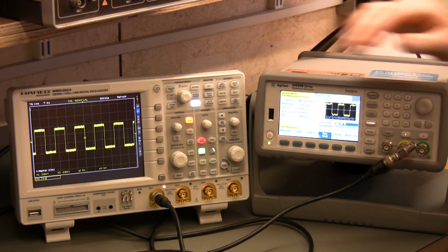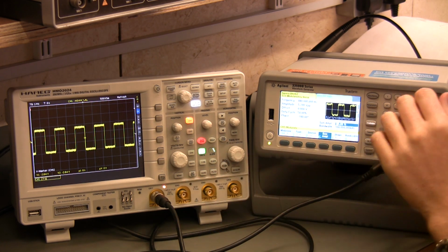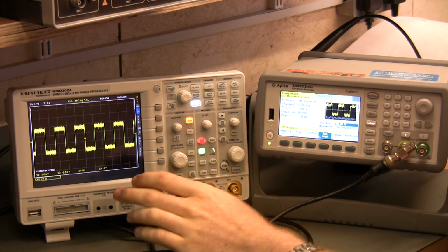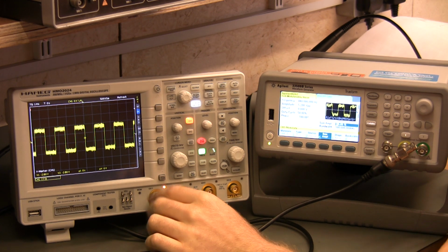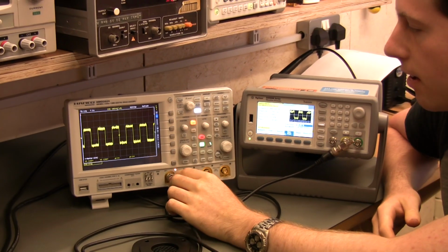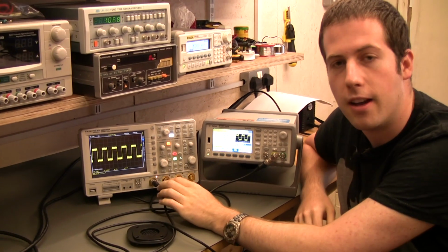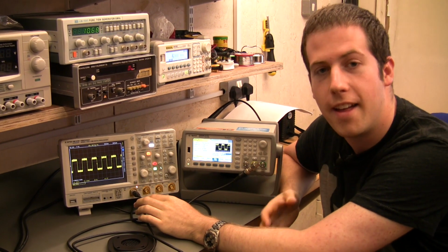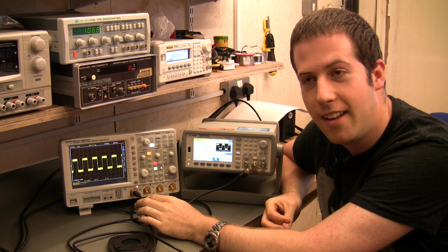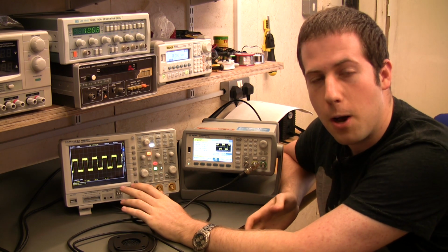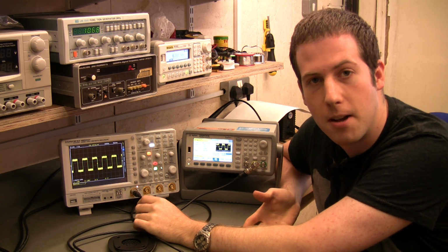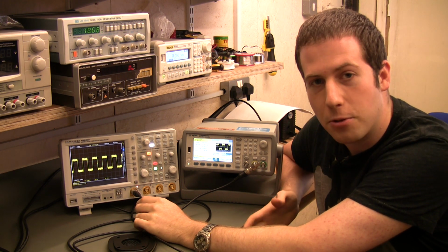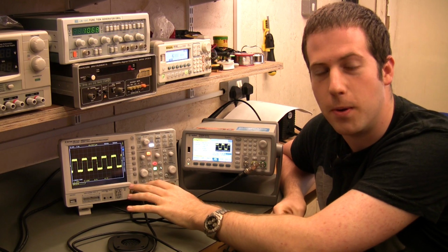Now the great thing is, if you want to test out a signal, and you want to test out your system, and you want to see how well it functions with the presence of noise, you can generate a signal. You can add noise to it under very precisely controlled conditions, and you can see if your system still works. So I've shown you here with the square wave. You can also do this with something like pseudo-random binary numbers. So you can chuck out a whole stream of binary numbers, you can add noise to it, and see whether your system still works.